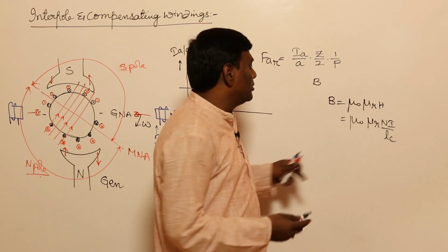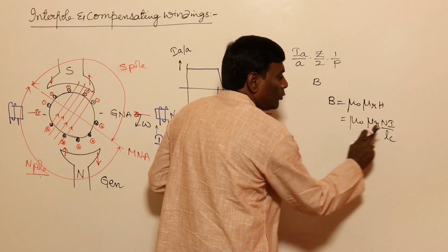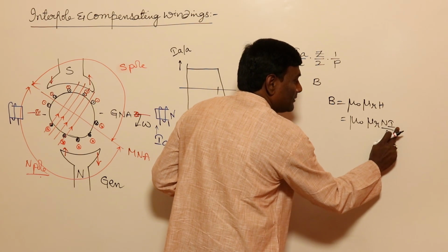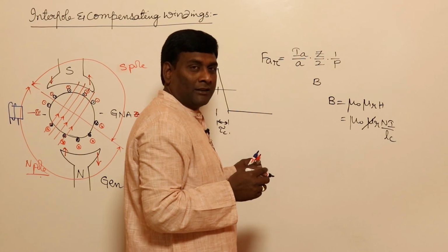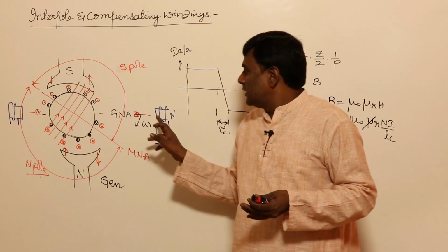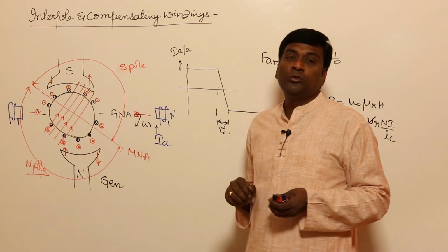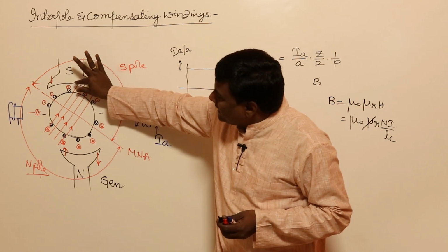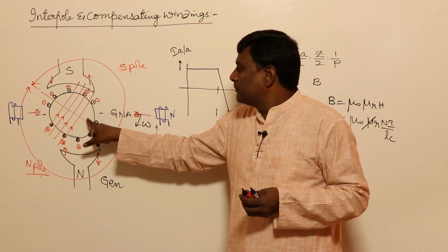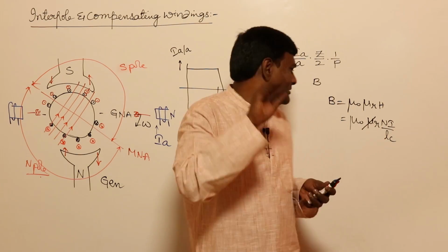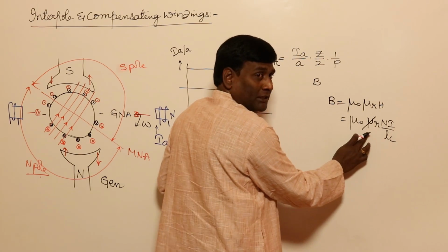Okay, so for example, what is the MMF required to compensate the air gap? Between the interpole and armature, one thing I may have to tell you here, the air gap length here will be very less, the air gap length here will be more, because of some reasons, forget about it. Relative permeability is going to be 1.